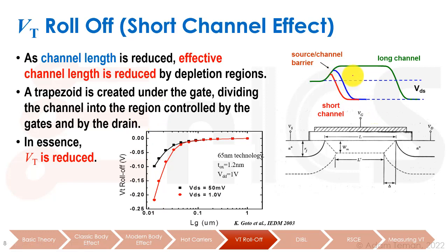Well, one way to look at it is this type of graph over here, where we have the source and the drain and the gate, and we have this potential barrier which causes the electrons in the source not to be able to run across the channel, even though we have a voltage drop, the drain having a lower energy than the source and wanting to pull these electrons, but they're blocked by the gate potential barrier.